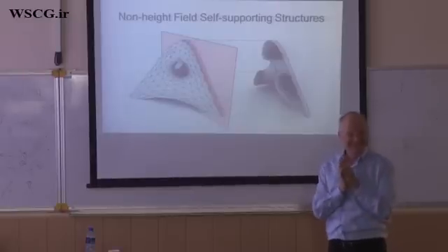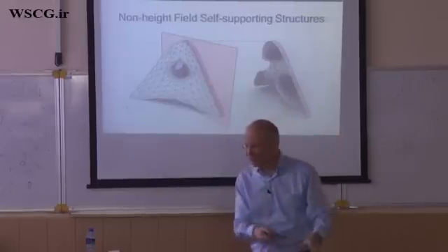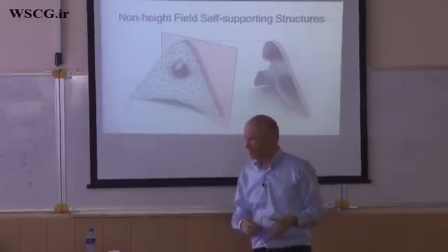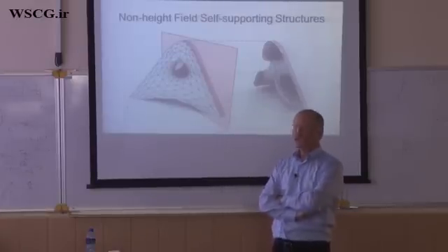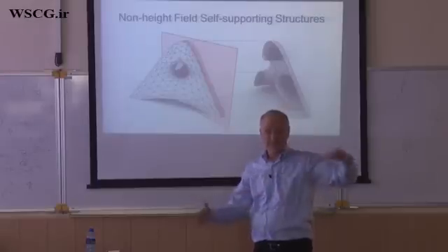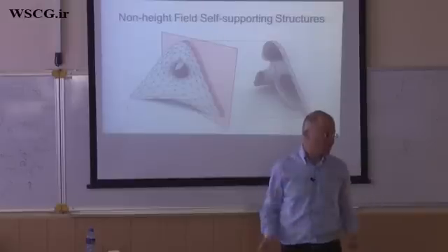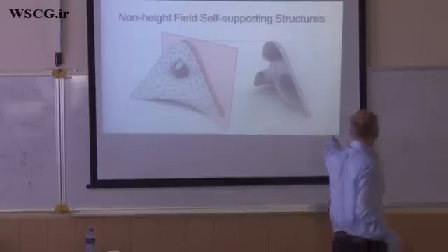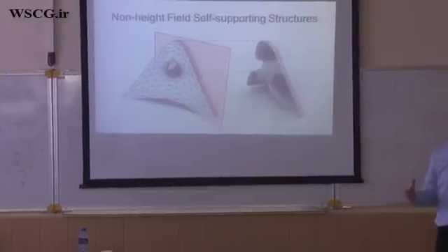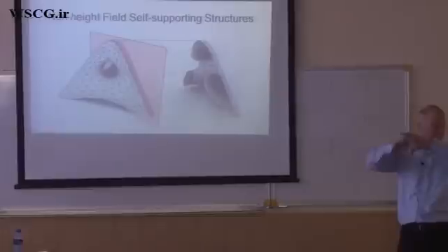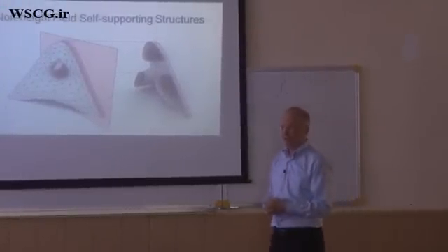Building it is another thing, because how do you build it? You cannot just start brick by brick and build it up, especially if you do not use mortar. You need a scaffolding. Then you can put your bricks, and then you have to remove the scaffold, which will be more or less impossible with this type of shape. So only at the very end, when everything is complete, you remove this scaffolding, and then it will stand.